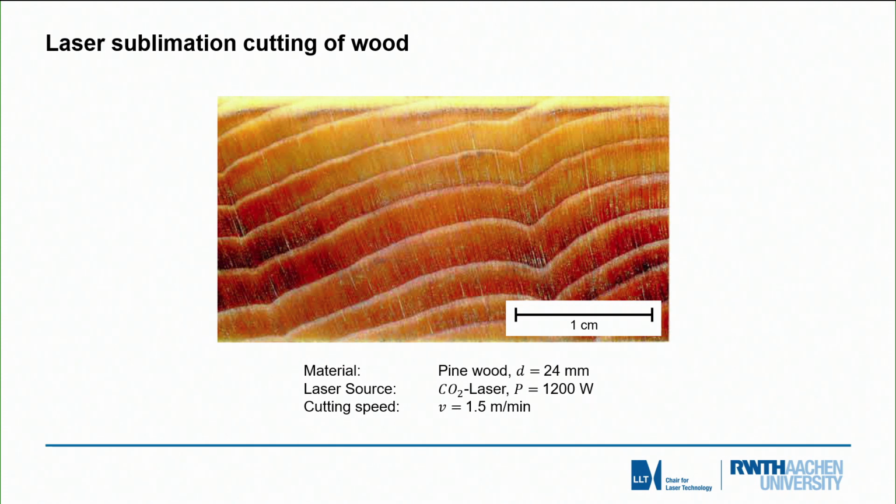As you can see, the surface looks quite not carbonized, and this is true, but not 100%. Actually, there is carbonization, of course, because we vaporize wood. And this carbonization is so thin that it is below about a micron, so the visible light does not resolve this carbonization film.